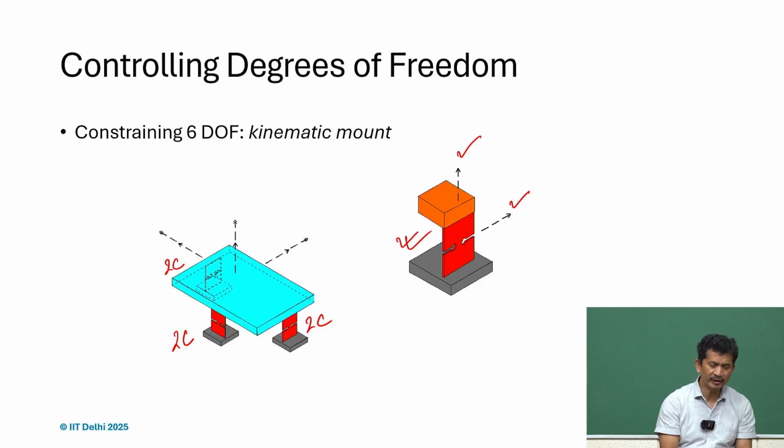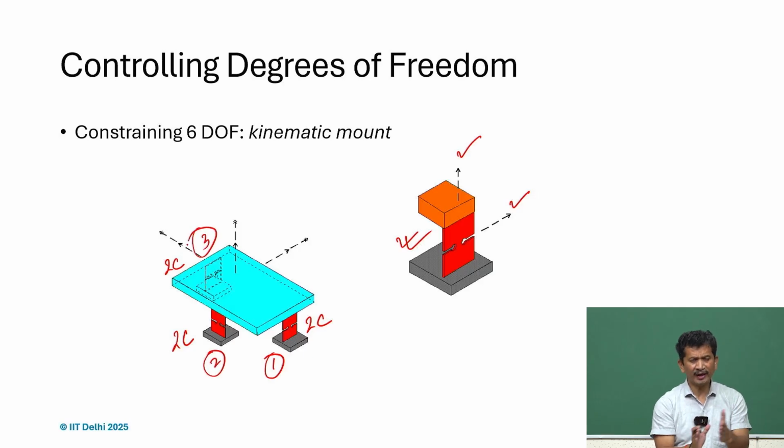Of course, the orientation. So, what you see, if I just say it is element 1, 2 and 3, 1 and 3 are parallel, but element 2 is not in the same plane. If it is in the same plane, what will happen is over constraint, because if you try to move, all will flex, all will bend, and then it will not restrict that motion. So, it is then an over constraint design.